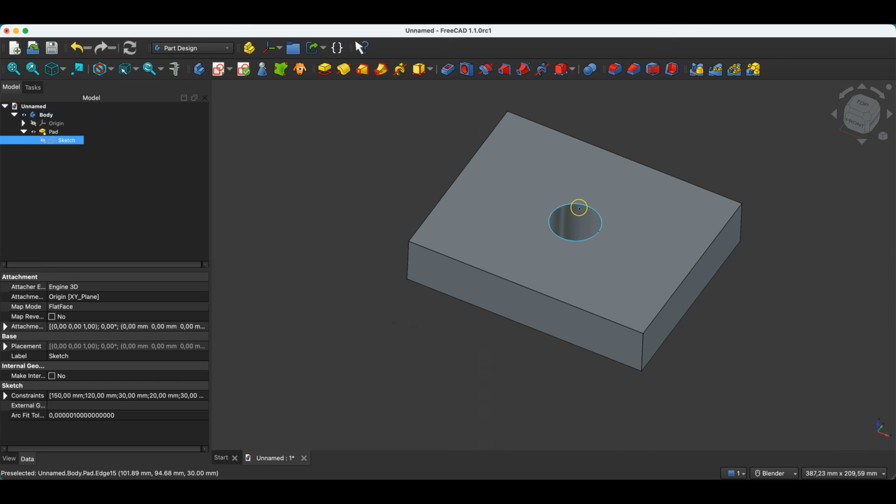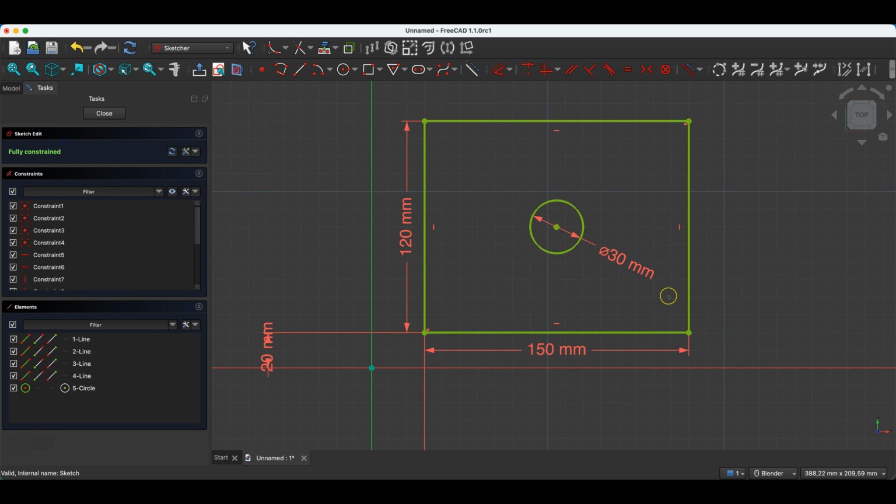We close the sketch, and the changes have been introduced to the solid, and this circle will always lie in the center of the rectangle. I go to edit the sketch, and here we just applied a geometric constraint. We assigned a relation between geometries, and this relation specifies that the center of this circle lies between the corners of the rectangle. This is one of the basic relations. Applying such relations in some cases will allow you to become independent of the model's dimensions.